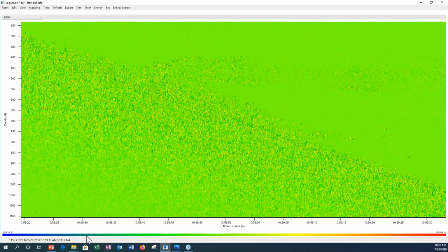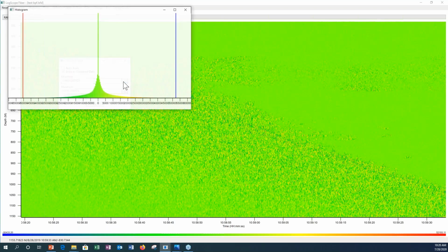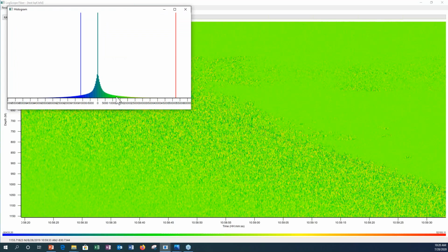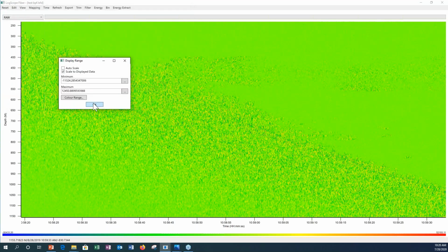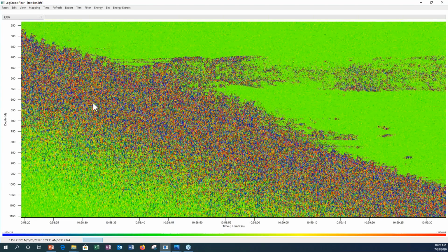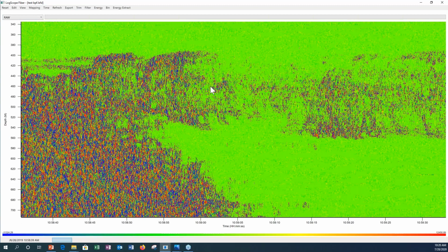We'll go down and select some amplitude distribution. In this particular case, because it has been bandpass filtered, it's a little bit better behaved in terms of the overall distribution, so we can squeeze in on that distribution a little bit and see if we can get a little more definition. And hopefully you can see that now we really have highlighted some of this energy that's scattering off of this tool descent, or at least being generated in that particular area of the well.